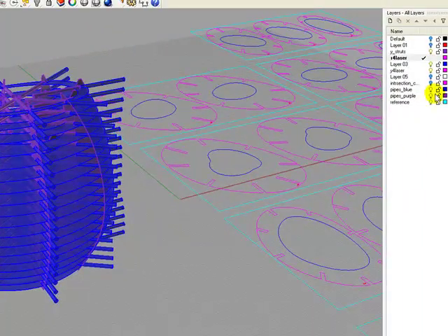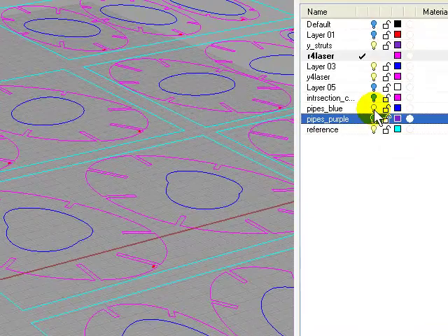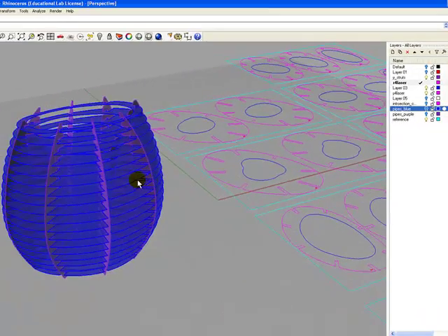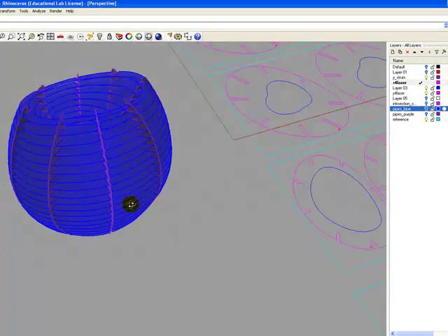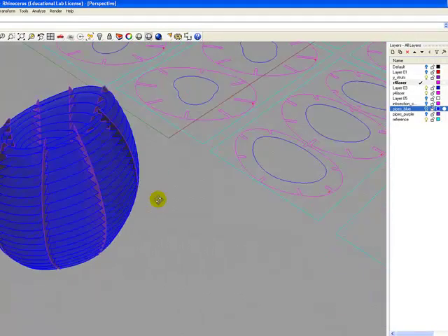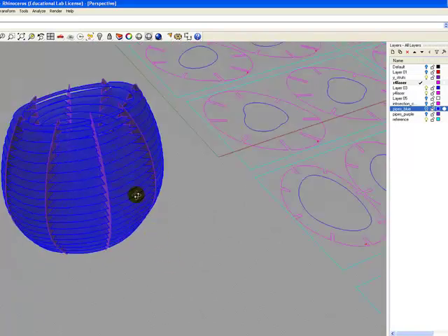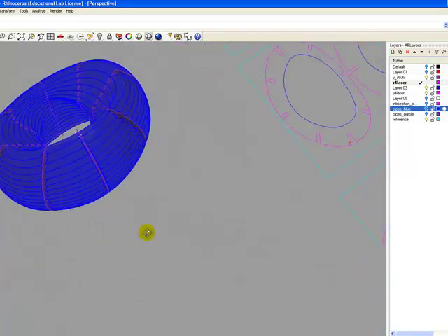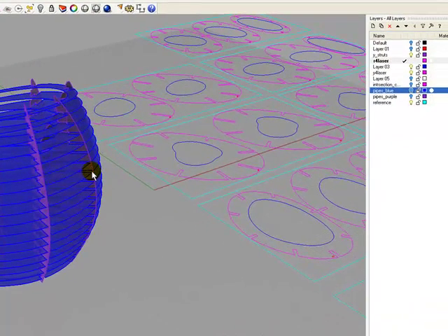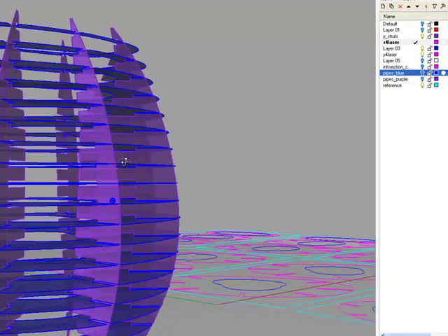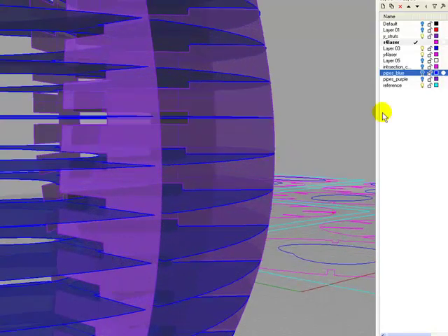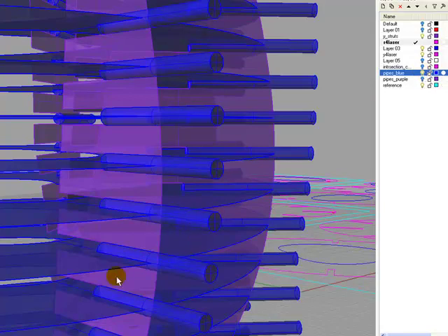And basically, let's step through this so that we can see how it works. Let's remove the pipes first. You use either the contour and the sectioning command to generate your ribs horizontally and vertically, in this case, after which you add these pipes. And if we look here, and let's rotate this up, we add pipes first to make our cuts.